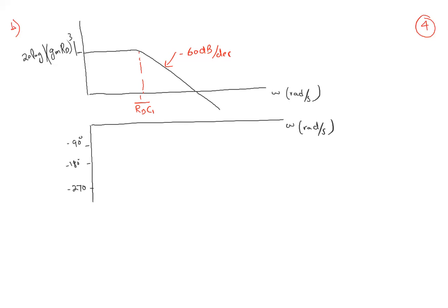And here it will be somewhere minus 135 because that is important for us, and this is omega p, 1 by 10, all are the same. So here it will start its ramp at this point, will reach minus 135 here, and will go onwards to minus 270, and then it will go straight. And its slope will be minus 135 degree per decade.